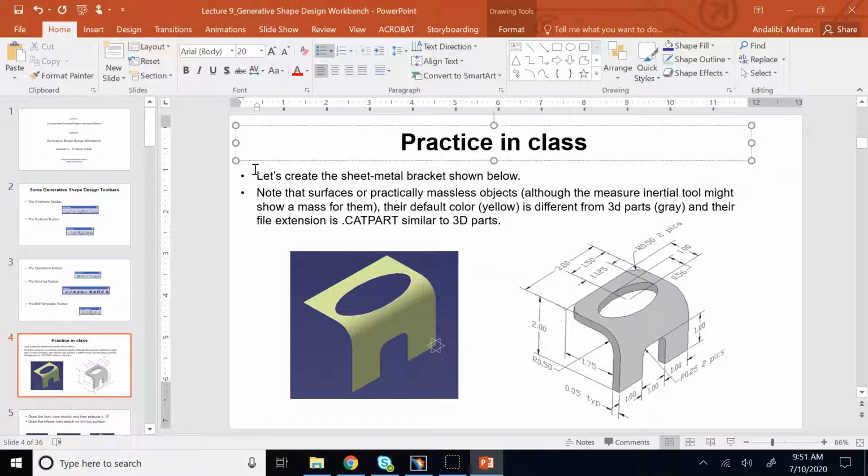When we want to create solid objects, we can start by creating the surfaces. And again, the reason is CATIA has so much flexibility and so many tools when it comes to forming surfaces that it does not even have when you want to create solid parts. So we can always create surfaces, then convert them into solid objects, and I'll show you.